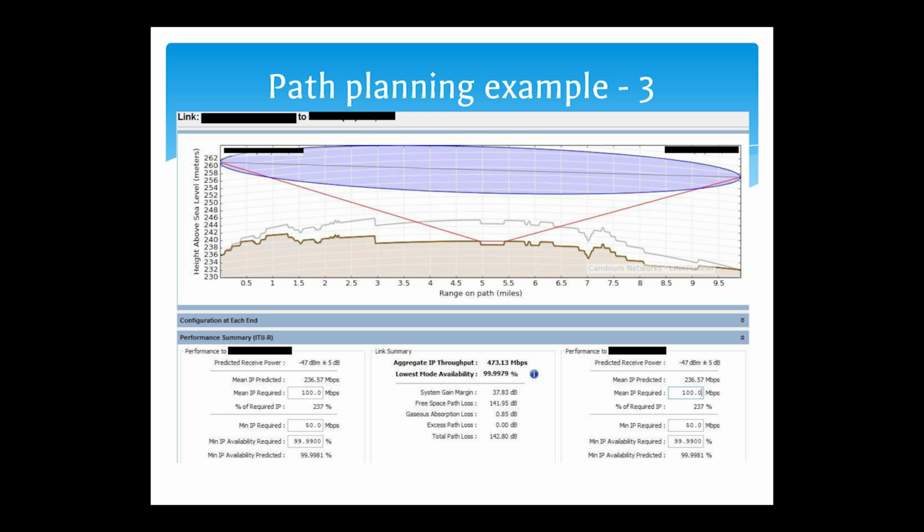This is different software that actually includes the speed in megabits. We put in the antennas and the GPS locations, and it calculates the signal level, and in cases of unlicensed systems where there can be interference, what speed you'll get depending on that interference.